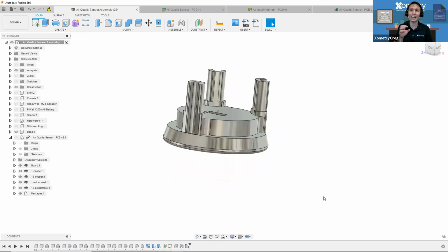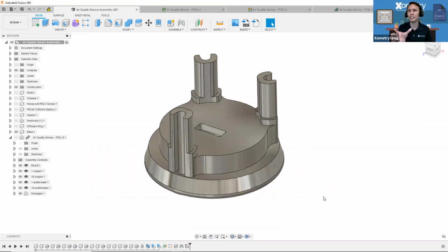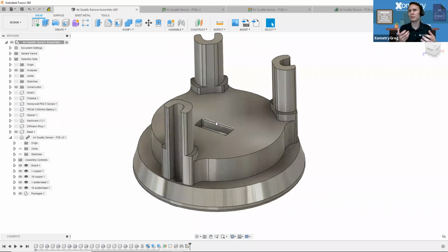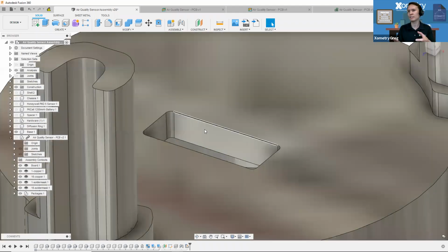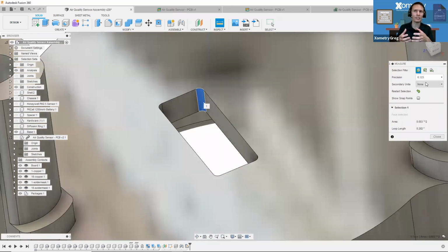Like, you could actually add $100 to this part, because you're increasing machine time on this. So usually I'm going to start looking at the biggest things, which are going to be drill depth ratios to radii. When I look at the pockets of the parts, that internal rectangular pocket, I'm probably going to be looking for at least a 32nd of an inch radii on that, because that's standard for a small tool that would be used to cut this.